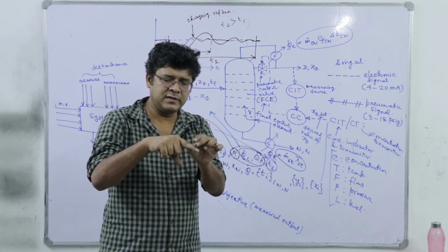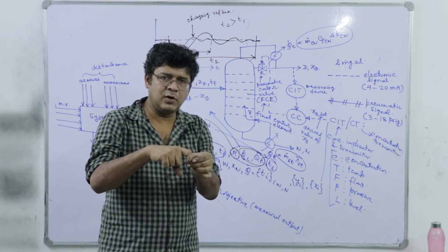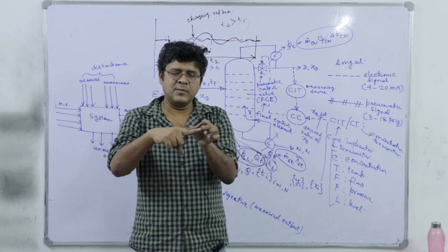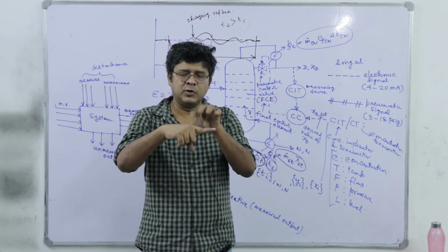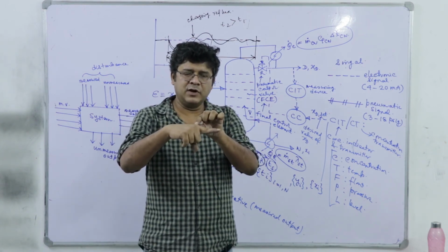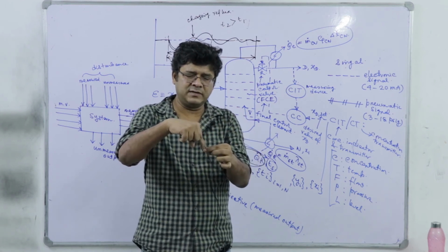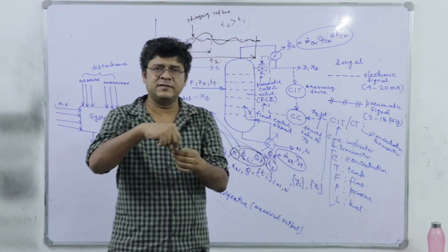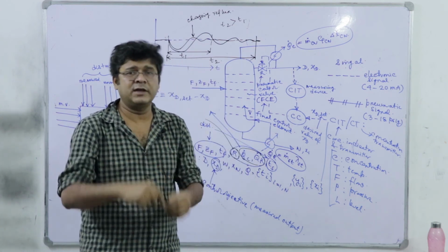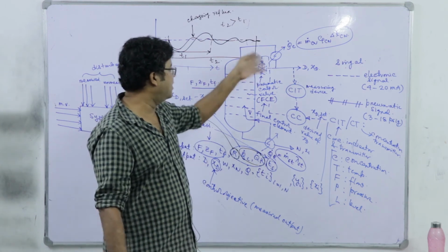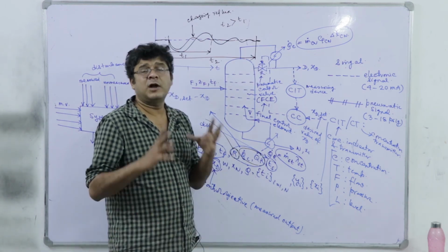So if it rotates, then this also may rotate, right. But if it is not so complex, say this segment is straight and here we have a stepper motor and the controller gives that, okay, you move by 60 degrees. So it will be moving by 60 degrees. So this is a typical application of control system engineering in robotics. Okay. So there the final control element must be a stepper motor, where here it is the pneumatic control valve.